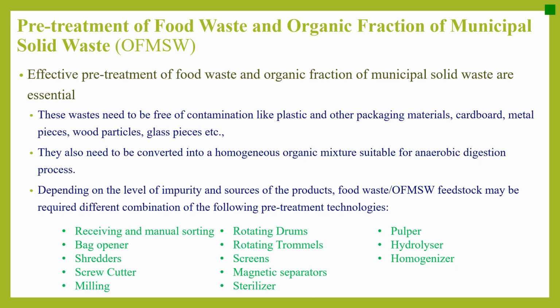So depending on the level of impurity and sources of the product, food waste and OF/MSW feedstock may require different combinations of the following pretreatment technologies: receiving and manual sorting, bag opener, shredder, screw cutter, milling, rotating drums, rotating trommels, screen, magnetic separator, sterilizer, pulper, hydrolyzer, and homogenizer.